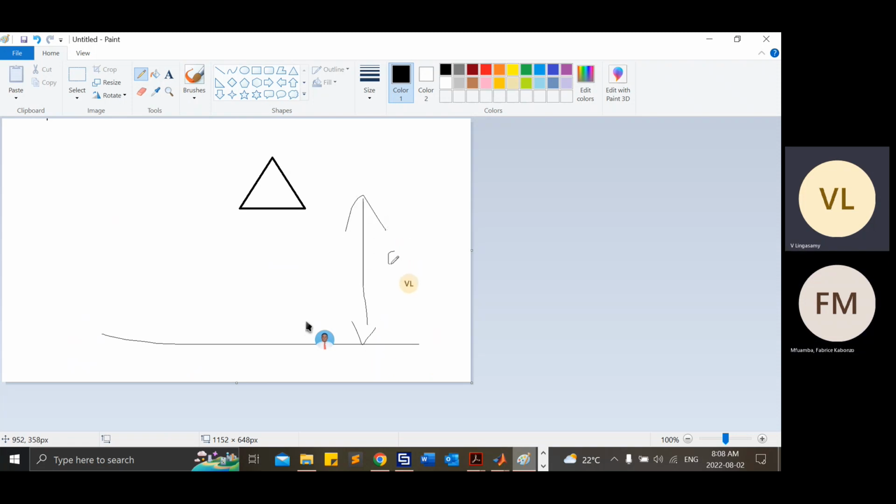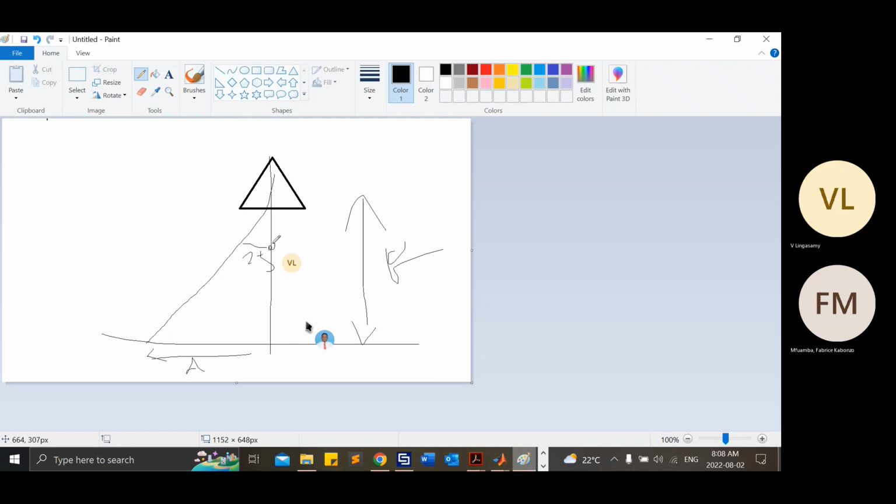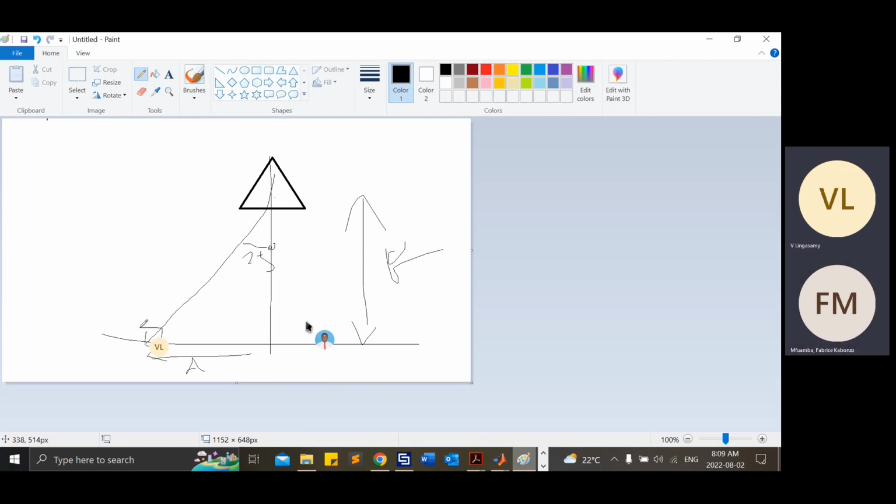Let's say the focal distance is F, and this distance is D. If you take tan theta with respect to this axis, it will be D by F, right? To see what excitation I am getting over here, it will be according to tan theta, where theta will be, for example, 25 degrees. This is the general pictorial representation, depending on the position of the horn, the reflector array and the element, of what excitation I will get.